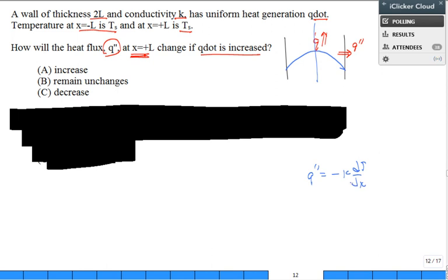If I look at dT/dx right at the center, it's 0. But a little to the right, it starts to go down, and as I move further out to the right, isn't it steeper and steeper? The steepness of that curve multiplied by the thermal conductivity is the flux.